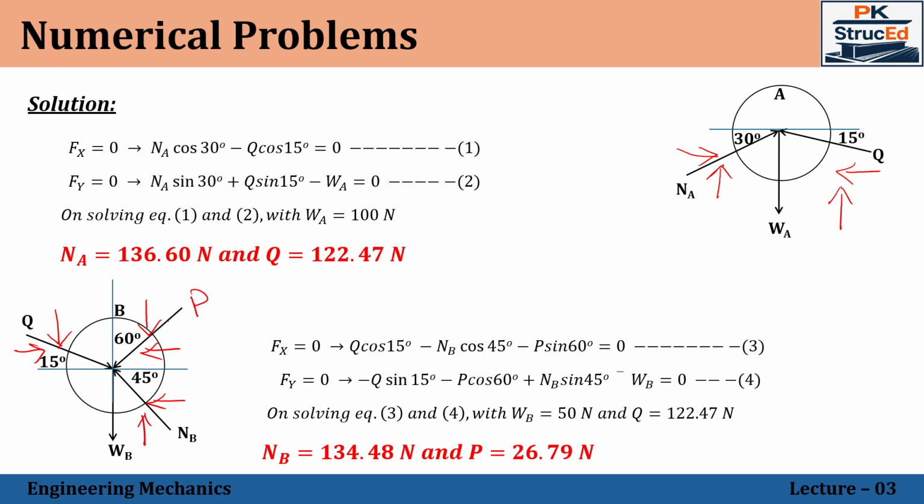To summarize today's lecture, you should always start with a correct free body diagram. You should identify all the forces clearly, resolve the forces into their components, apply the equilibrium equations systematically, and solve numerically without skipping any steps. This method forms the foundation for trusses, frames and structural analysis.